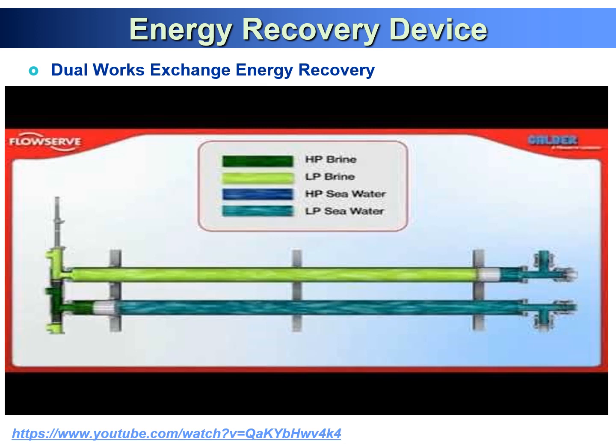So pressure exchanger is the most widely used energy recovery device. We also have another energy recovery device, which is dual work exchange energy recovery. Similar to the pressure exchanger, it requires just the high pressure of brine. This is the low pressure seawater, and we have some media here. When you have a high pressure brine, it pushes your low pressure seawater, and then this pressure energy can be transferred to the low pressure seawater, and this goes to your RO pressure pump.